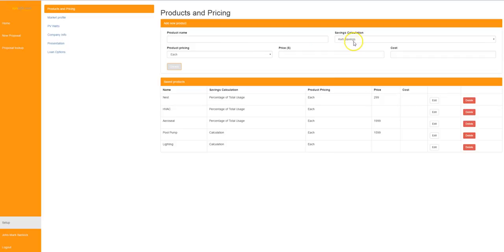You're going to use that option to calculate the savings, and what the system will do is it will calculate the energy use difference between the low monthly bill and every other month in the year, and the system will make the assumption that your low bill is indicative of the home's general use without any heating or cooling costs. So if you have a customer that was away on vacation and they have a very low bill that is not indicative of their baseline energy use, then you need to make the appropriate adjustments because the savings calculations will be off. The third option is a calculation type.